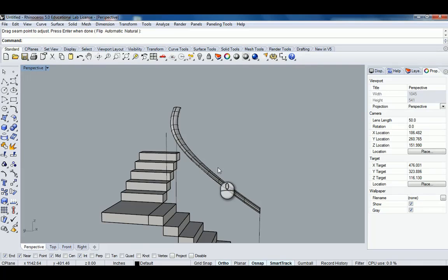So it's trying to say, all right, I have this complicated extrusion that doesn't have edges. You're trying to, with one curve, have it turn, and the tolerance is too much. So you need to be mindful of a lot of factors there. But sweep 2 with the right amount of guides should more closely solve that.